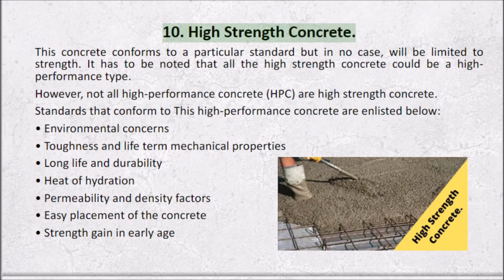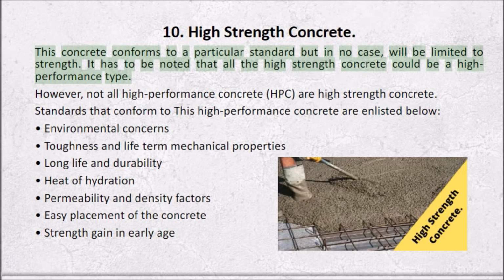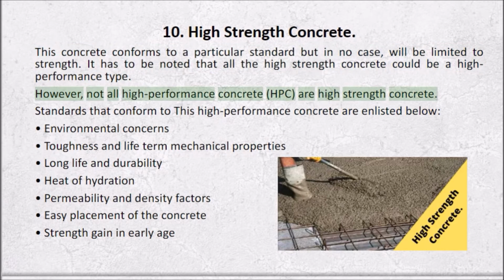10. High-strength concrete. This concrete conforms to a particular standard but in no case will be limited to strength. It has to be noted that all high-strength concrete could be a high-performance type. However, not all high-performance concrete, HPC, is high-strength concrete. Standards that conform to this high-performance concrete are enlisted below.